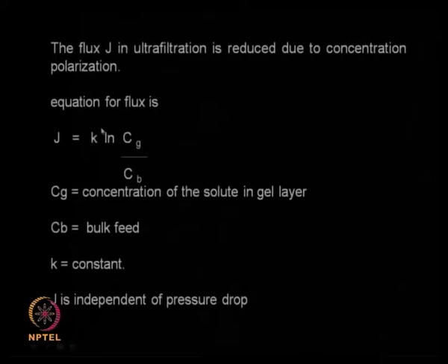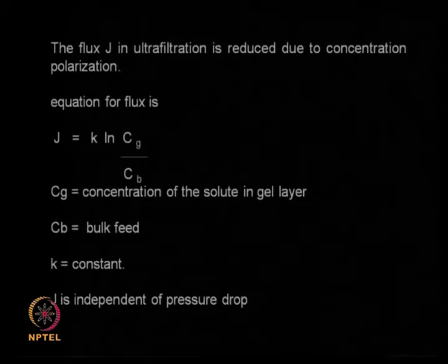So K is your constant, and now here you see J is independent of the pressure drop. So the pressure does not come into the picture in ultrafiltration, whereas in microfiltration pressure plays an important role, it is almost like a normal filtration. You see the difference? Okay.